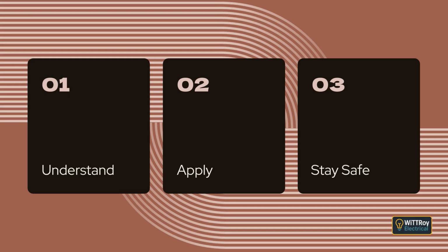Clause 2.3.3.2 Number of main switches. This clause explains that we should only install the number of main switches that are needed for safe and effective operation. In a normal home, you usually need only one main switch for the whole installation. If a building has separate metering for different parts, or different tenants, each part must have its own main switch so it can be isolated without affecting others. The aim is to keep things simple but still provide safe control where it is needed.